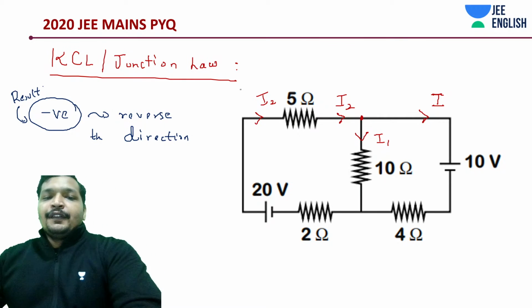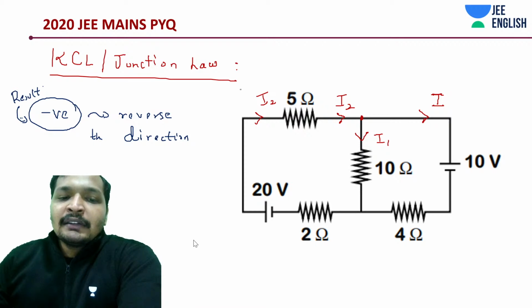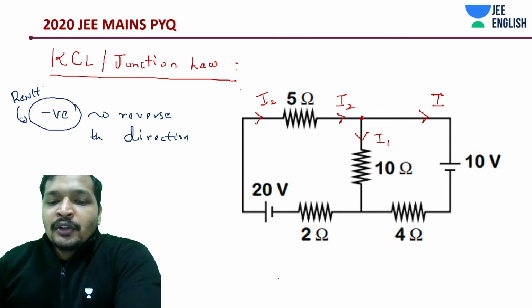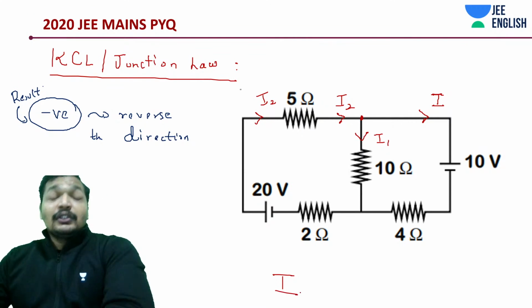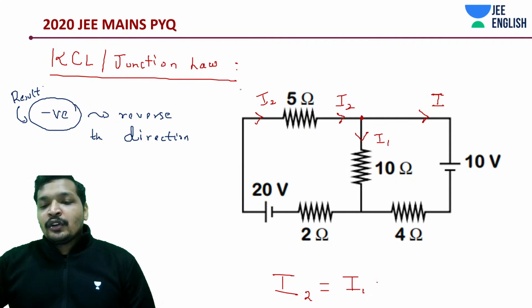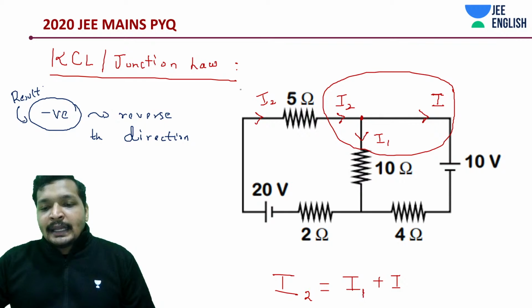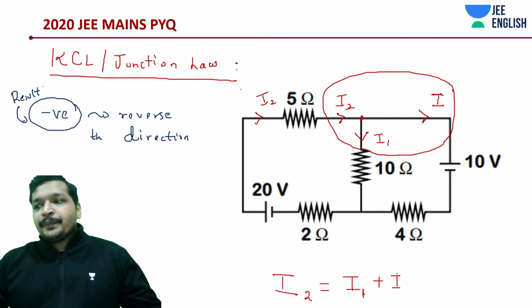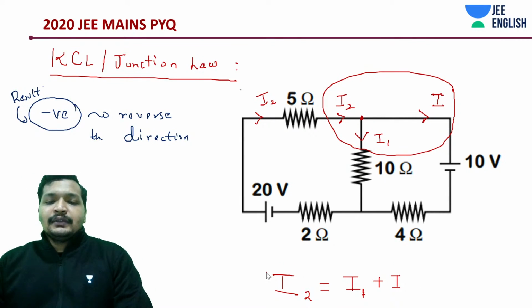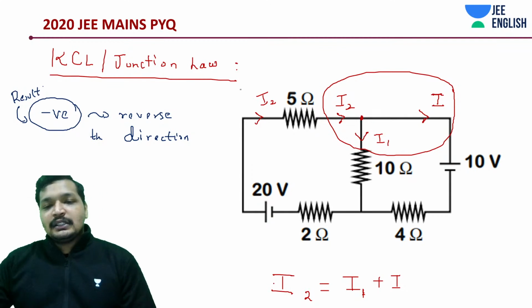Alright, now, first of all, I told you apply KCL, because you need to assume some current even to solve KVL. The moment you assume, you solve that. What is the big deal? Write down the KCL: I2 is equal to I1 plus I. That's it. Simple. I'm taking I because it's unknown. You can take it to be X, whichever you're convenient with. In your exam or during your calculation, you must be more convenient while doing the unknown based questions. You can take it X, Y.